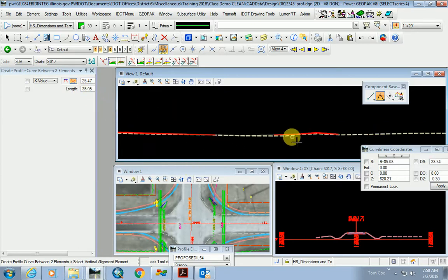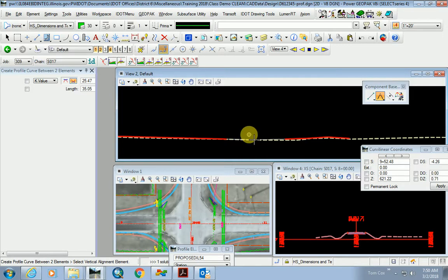And in this case, you're so close, you're at a stop condition, so design speed is probably less of a factor in this particular case, because you're right at a stop condition. So it might be more of a matter of what vertical curve length works out well, and you do want to usually not have some oddball vertical curve length, but it looked like something like 30 foot might work well. And sometimes it's a little bit of a trial and error.